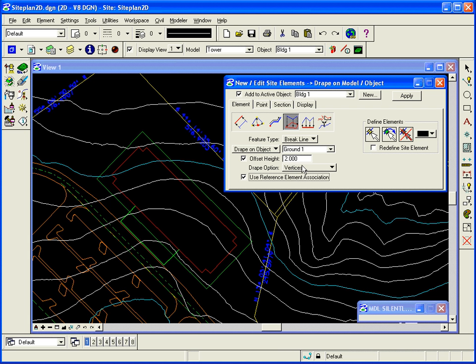And then I want to use, in this particular case, as you can see the contours in the view, they're sloping down, or up, really. We're going down grade as we go up the screen. So in this area the elevation varies all throughout the shape, and I want the shape to be a flat surface. So I want it to calculate elevation at the highest elevation that it finds in that red shaped area. So I'm going to set it to maximum.